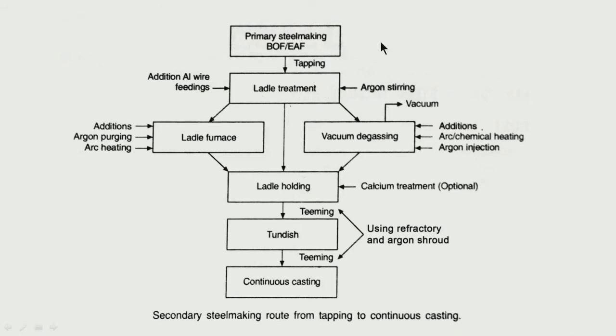I have mentioned we have to be careful about the slag carried over. Slag from primary furnaces should not be allowed to come during tapping. There is a possibility of slag coming towards the end of the tapping because of funnel formation, I have mentioned. So we must have a slag stopper, not to allow the slag from getting carried over to the ladle. Otherwise this will create problems, because this slag has a high amount of iron oxide, some amount of manganese oxide, some amount of phosphorus oxide. This will create difficulties in subsequent secondary refining processes.